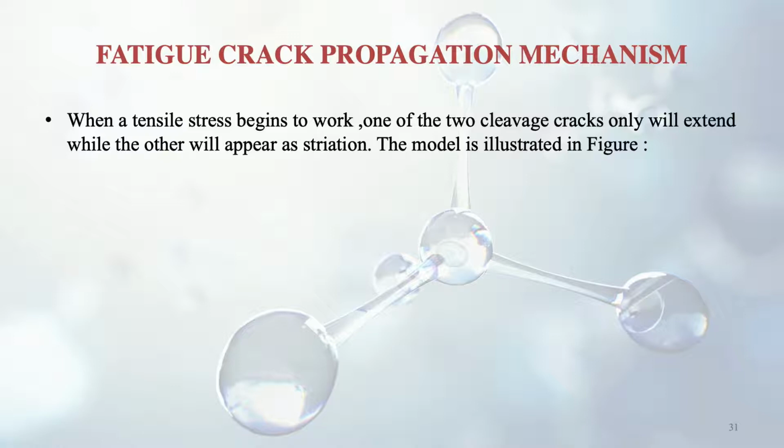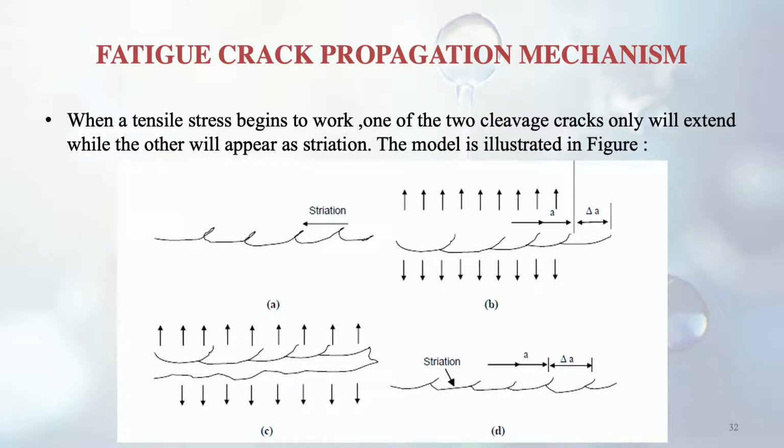Now in these figures you can see, when a tensile stress begins to work, only one of the two cleavage cracks will extend while the other will appear as striation. You can see in the figure here. Only one of the two cleavage cracks is extending, the other one will remain as such.